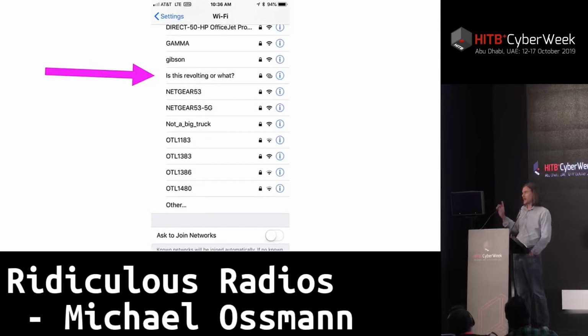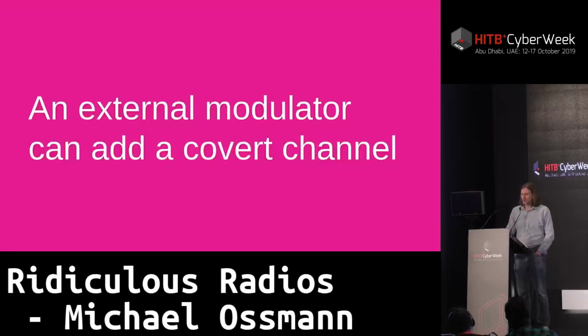So this was actually a fake Wi-Fi network produced by a Bluetooth dongle. It had no capability to transmit Wi-Fi. It was just transmitting an unmodulated test carrier, and then we were switching back and forth between two different length delay lines. With that simple technique, we were able to improvise something that could transmit data that was seen as a Wi-Fi beacon by my phone.